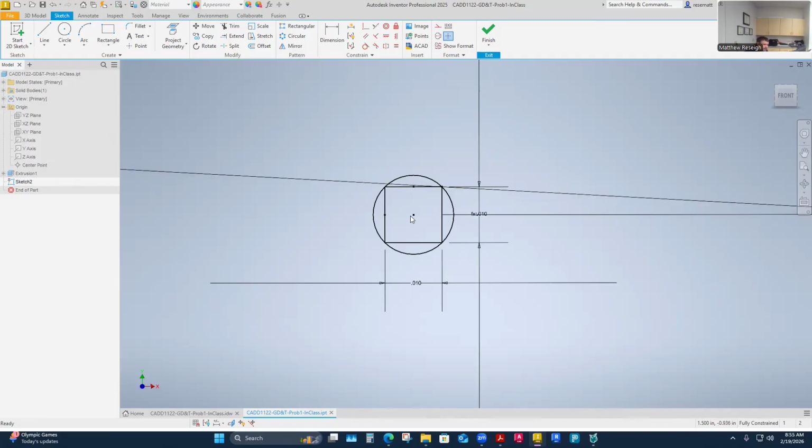So now, whoever has to put this hole in there, if you're holding them to a tighter tolerance by using a rectangular coordinate plus-and-minus type dimensioning, you're giving them actually the ability to be sloppier, which sounds scary, but we're actually giving ourselves more parts that are acceptable.